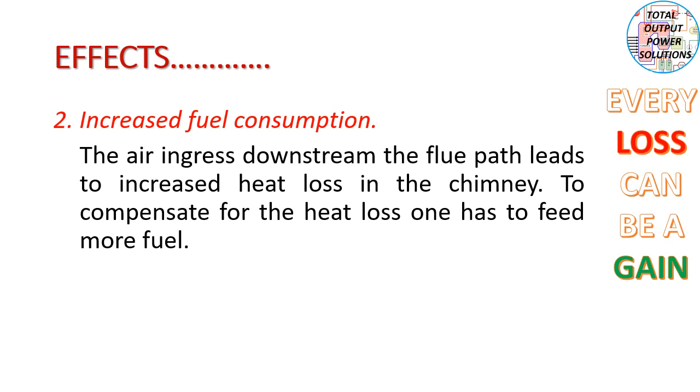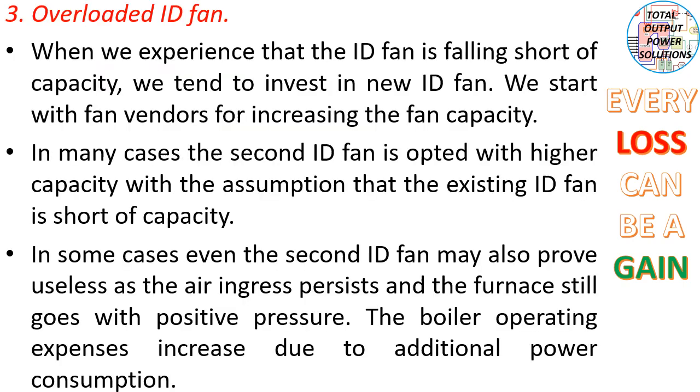The second effect is increased fuel consumption. Air ingress downstream in the flue gas path leads to increased heat loss in the chimney. To compensate for the heat loss, one has to feed more fuel. So the fuel consumption increases.